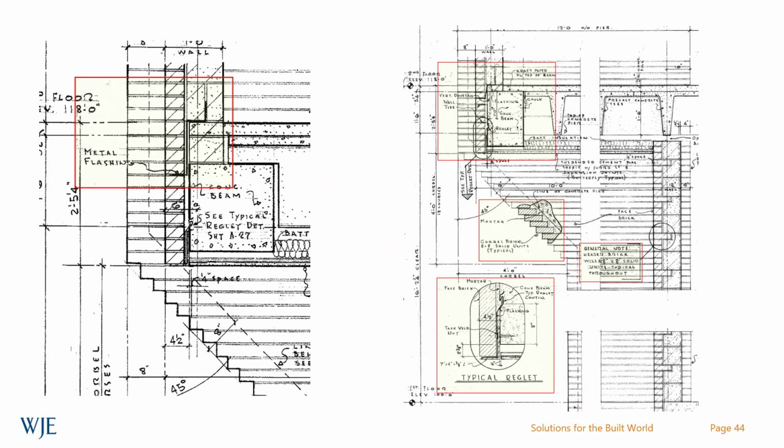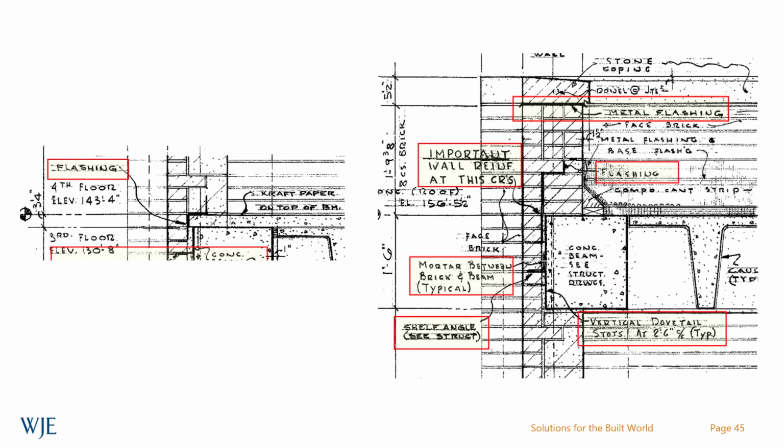This is an architectural detail of a section through the haunches that shows the structural support for the brick cladding system, as well as the concrete structural system behind the haunches that create the elements. This is the detail at the top of the building, showing how the brickwork is integrated into the structural system and the CMU backup in the flat wall sections.